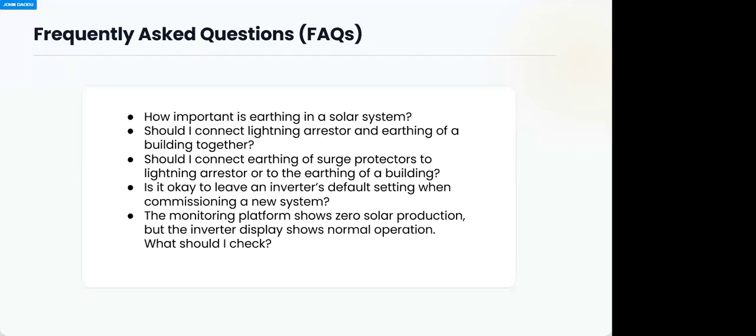Okay, so it's better to copy the original settings out and keep them. So when you make any adjustment, you can always trace your way back. If you make an adjustment and the inverter is now going on, off, on, off, when initially it wasn't doing that, you were trying to set charging, and now you have changed something and it's doing something even worse than what it was doing before, then you can say, okay, let me return it back to the default.